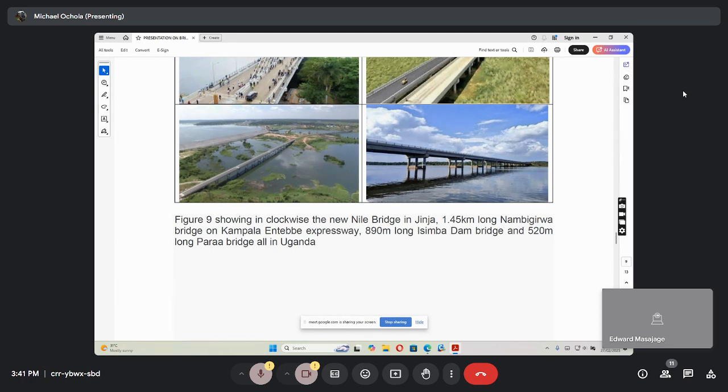You can have a solid type, you can have a wall type. A wall and a column are different, you can read about a wall and a column. If the width exceeds maybe 6 meters, it qualifies as a wall. If it is less, it may be a column. We can look at it and make corrections later. So you can have a solid type, a wall type, and a column type. You design all to be adequate to take on the water problems, floating vegetation, and lateral load. Then you look at economy, constructability, environmental friendliness, all that.